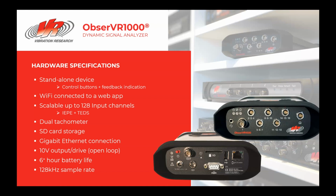While the VR9500 controller and Vibration View software are designed to create, control, monitor, and report on lab tests, the Observer 1000 and ObserveView products are designed to collect, analyze, and report field test data. The Observer 1000 is a mobile, battery-powered standalone device. It has inputs for microphone, GPS, tach signals, and easily measures acceleration, pressure, strain, load, etc. Several of its significant features are listed on the slide.